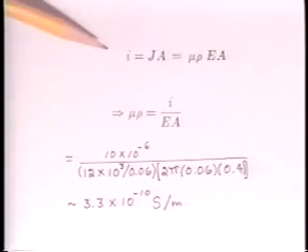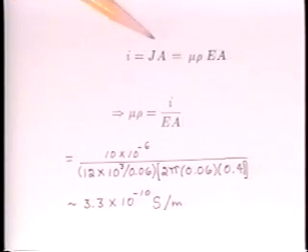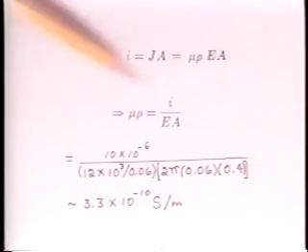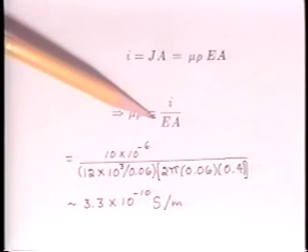This total current is the current density at the outer wall multiplied by its area, A. The current density is in turn the product of the mobility, the charge density, and the field intensity at the outer wall. So the effective conductivity is the total current divided by the product of the field intensity and the area.